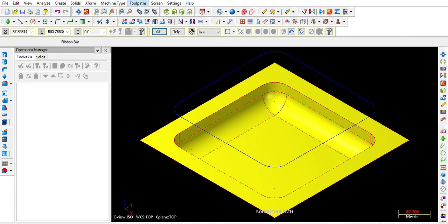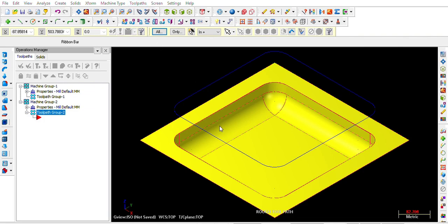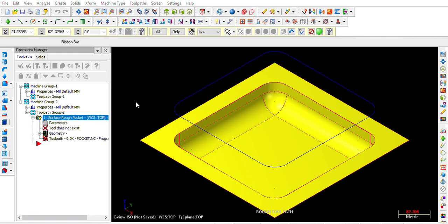So for generating toolpaths here, I need to first pick up the machine default type. So toolpaths, yeah, toolpaths. In this, surface rough pocket. So pocket milling is being done on all surfaces. Rotating surface, I will pick up this object in containment chain.